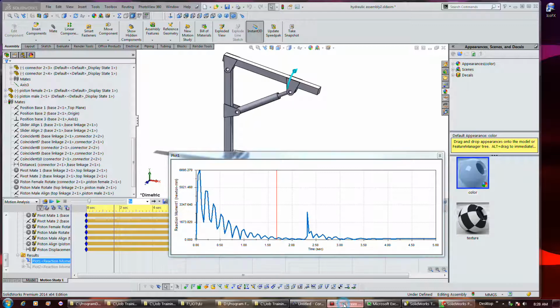But anyway, I was going to say that looking these over, the mates that they're changing are actually pretty conventional. I mean, that's exactly how I would be inclined to assemble these things. That's a concentric mate, and that's a coincident mate. These are really a bunch of standard mates, but they're calling these redundant, and that's not the word I'd use because that's required for minimal constraint.